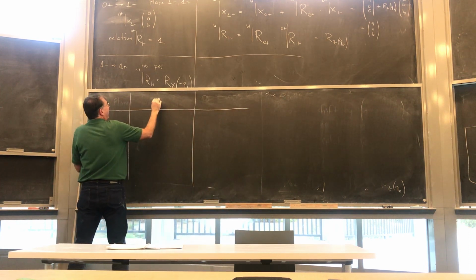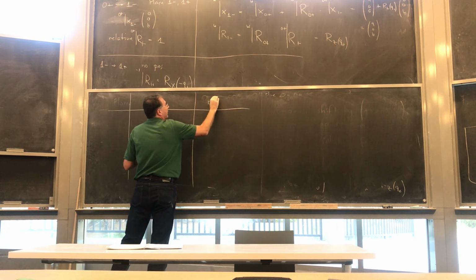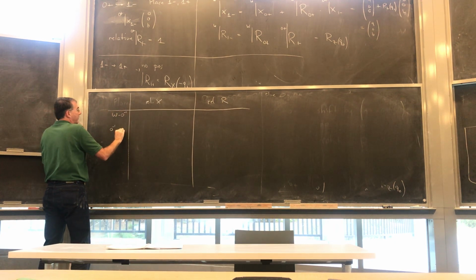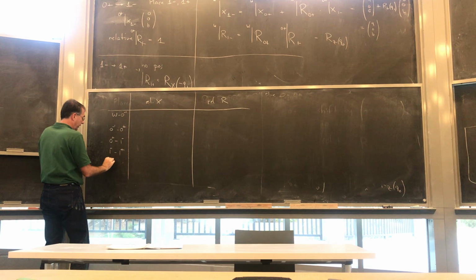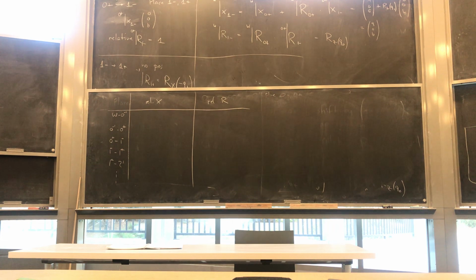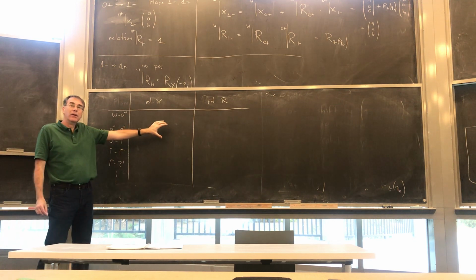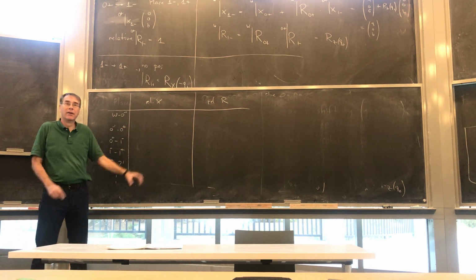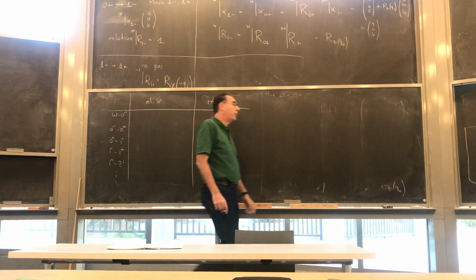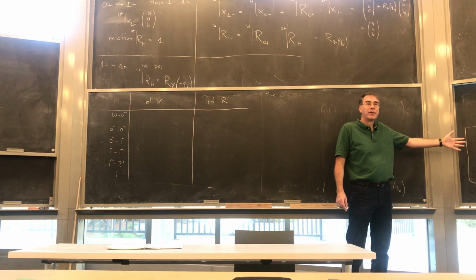That is basically going to be a table that says, okay, what is my x, my relative x? What is my relative r? From world to 0 minus, 0 minus to 0 plus, 0 plus to 1 minus, 1 minus to 1 plus, 1 plus to 2 minus, etc., right? And basically it is going to be a walk, rotate, walk, rotate, walk, rotate, walk, rotate. And that table will contain the lengths, right? And it will contain the rotations. And basically once you have that table, run a loop over it by those formulas. And that gets you out to the end.